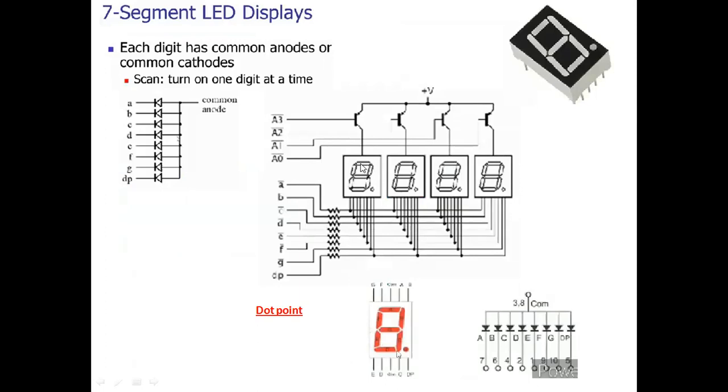In the last part, we have seen an individual LED. In case of the 7-segment LED display, the circuit is as shown here. So we have this common anode type of LEDs used here, where the anodes of all these light emitting diodes, starting from A to G along with the decimal point, have been shorted, right?